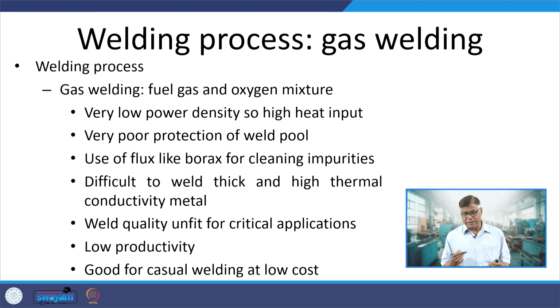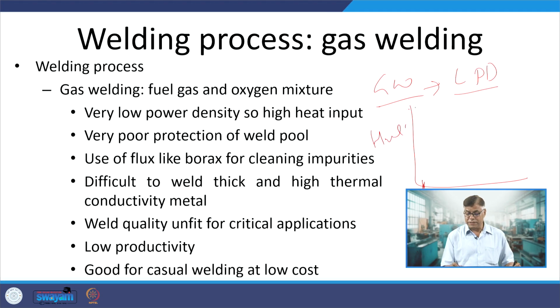So, starting with the gas welding process, we will be talking about the different aspects. Gas welding is considered to be a low power density welding process, and because of the low power density, the net heat input that is required for welding by gas is very high as compared to that of, say, arc welding or laser welding.